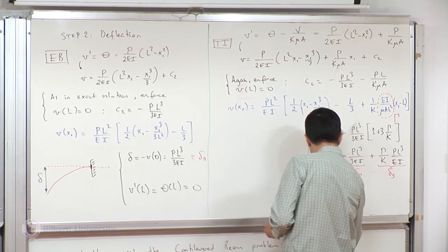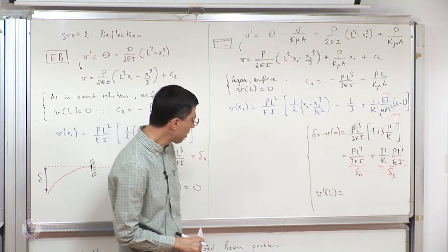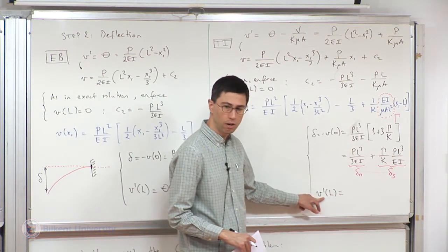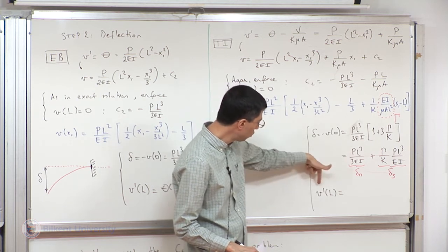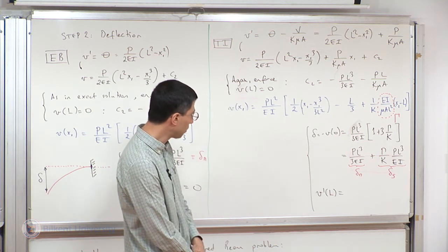And moreover, as in the exact solution, the Timoshenko beam theory differs in the description of the rotation of the vertical plane and the slope of the neutral axis deformation.